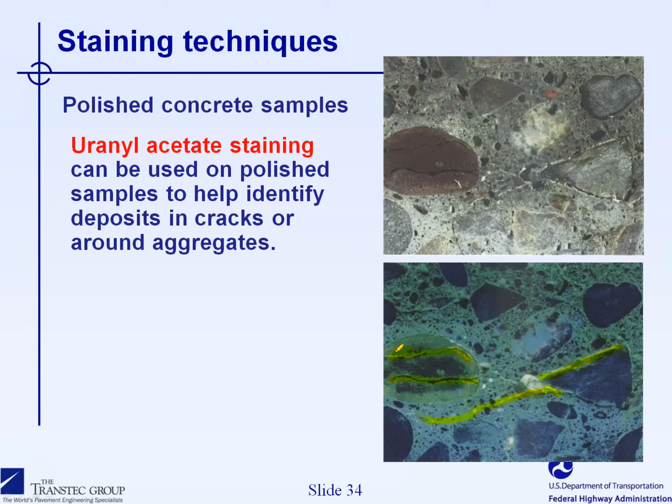So there was possibly alkali silica gel present here, and that gel may have been leached out during sample preparation, because you see that the crack is fairly open there. When you have open cracks like that, those cracks are more prone to the gel disappearing during sample preparation. But this actual slide is a very limited portion of the concrete. So there might be other areas where the gel will actually run into the aggregate particle.